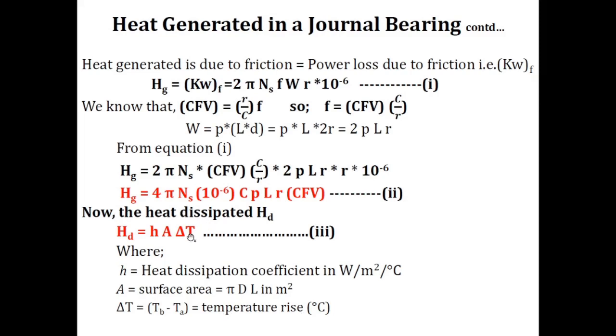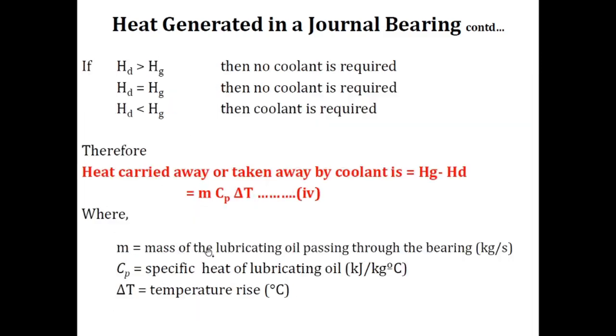So here, students, you just think of how you can increase the value of this Hd. That you will understand by this. What would happen if the heat dissipated from the bearing is greater than the heat generated? It means there is no problem of overheating, so no coolant is required. If both are the same, then also there is no problem, so no coolant is required.